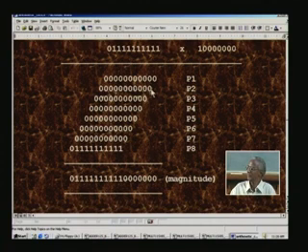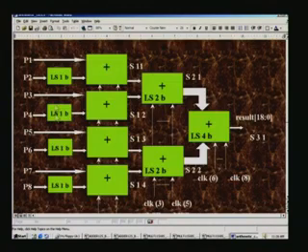So that is precisely what we are doing, not only for P2 but also for P4, then P6 as well as P8. So you will see a left shift by 1 bit as far as the first stage of addition is concerned, you can see here. So P2 is left shifted by 1, then only added to P1, and here when this is clock 1, corresponding to this there will be internally a register, and that will register the sum of the LSB alone.